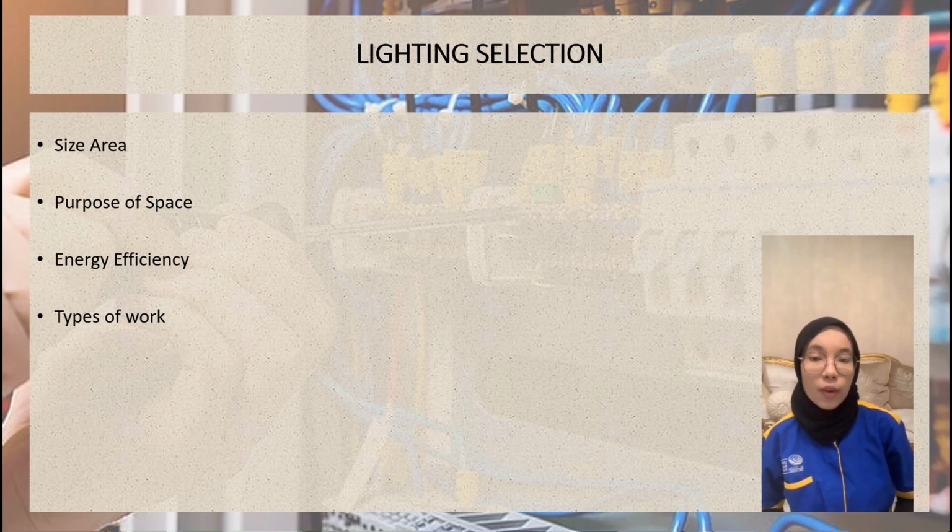reasons. First is size of area. A relatively small area and less lighting needs to be provided adequate lighting for the space. A combination of 1x18 and 2x18 watt fluorescent lights provides uniform and glare-free lighting throughout the room. This is because the majority of the space in the office uses 2x18 watt fluorescent light. After all, it has a ceiling size of 600 by 600, for example, the meeting room, the district engineer room,